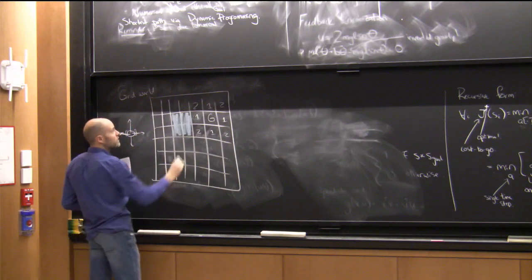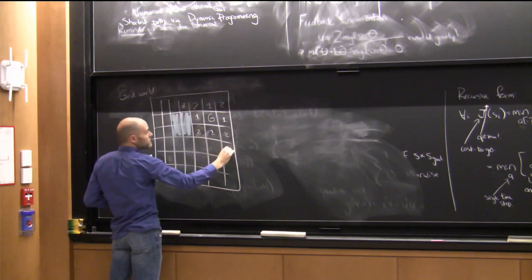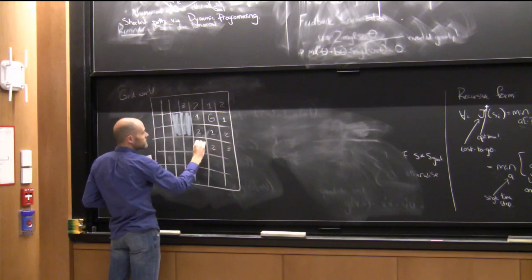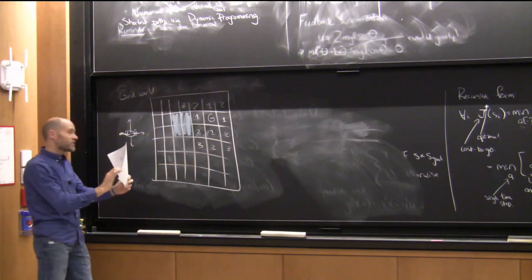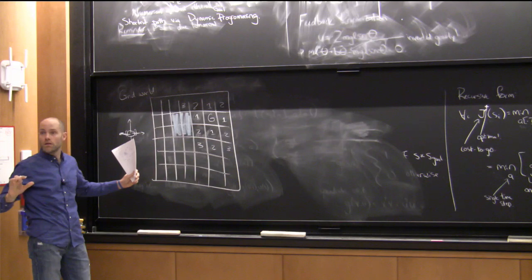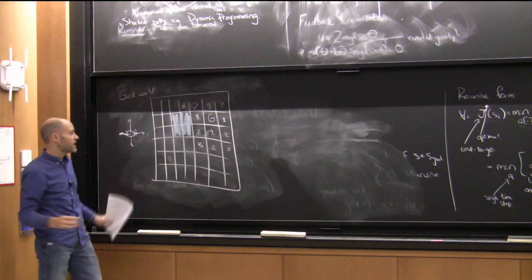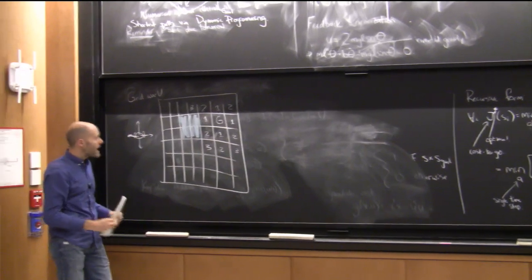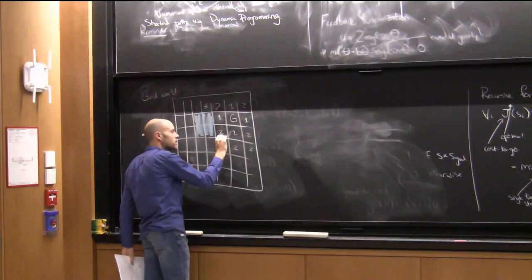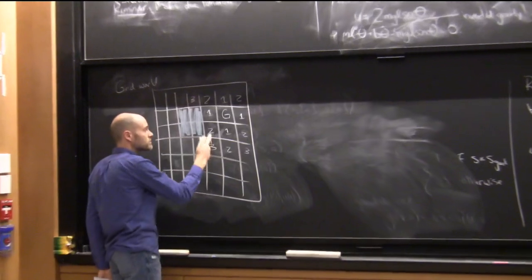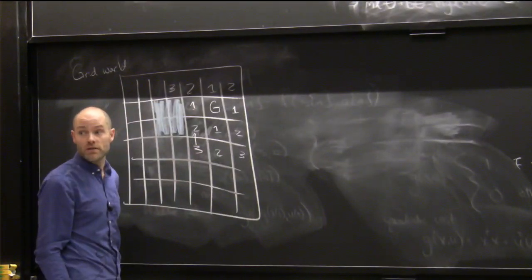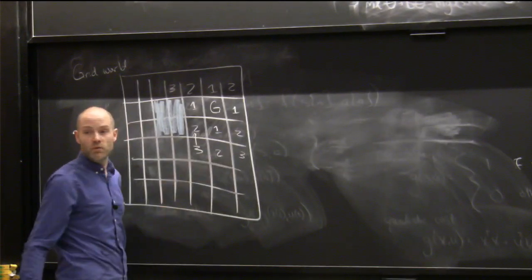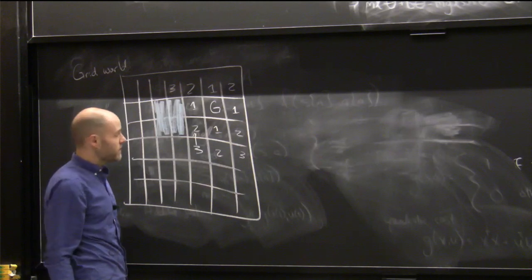On the third pass of the algorithm, I'll figure out my 3s, right? I missed that one in a second, right? And I'll slowly propagate out a solution that tells me how far I am from the goal in terms of distance, right? The policy then, once I have that, is just a map that tells me go downhill in cost. From where I am, pick the direction that takes me down in cost, right?